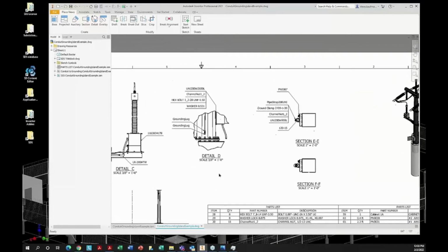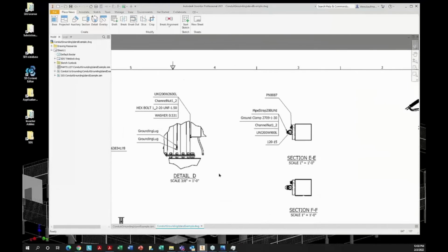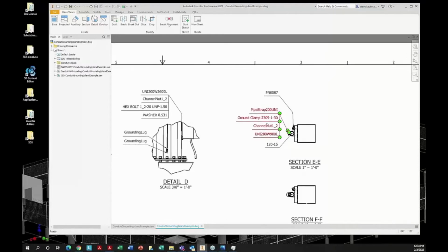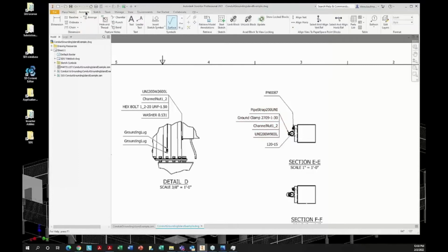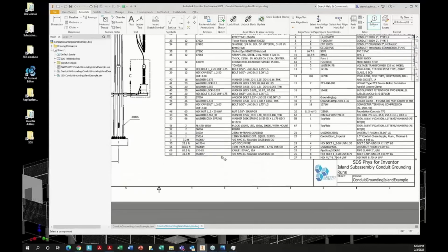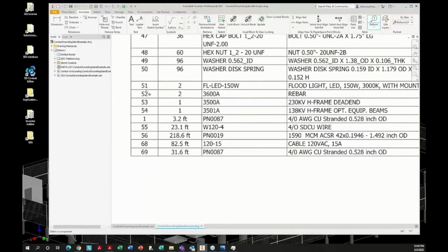The other thing I'm doing here, I have a new document I'm working on, is this type of idea. Instead of coming up with an item number on here, the old way, you want an item number because you don't have enough room to add those 400 balloons. Here we can add the actual part number in the balloon. So for the balloon style here, I come over to annotate. I want a balloon. I want to use my line balloon. This is edited and made, and there's my line balloon. So it's 121.15. So I look up 121.15. Here it is here. I don't need the item number.